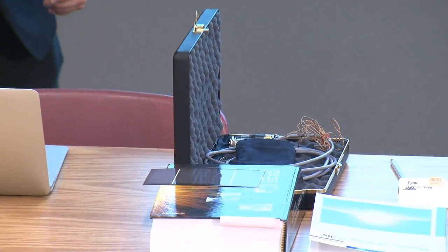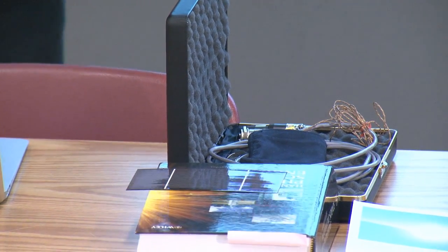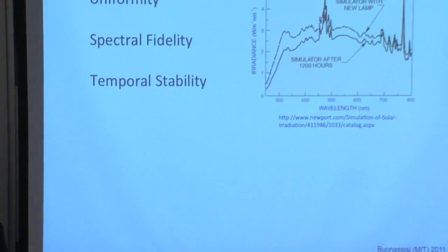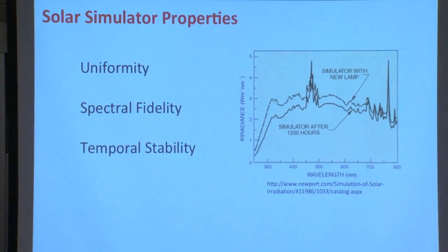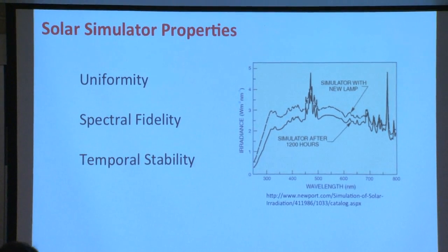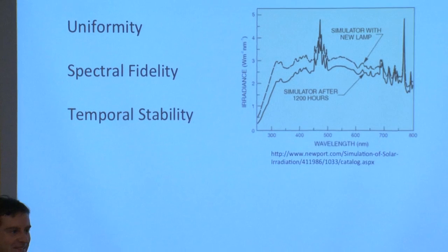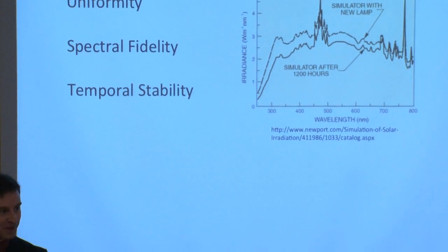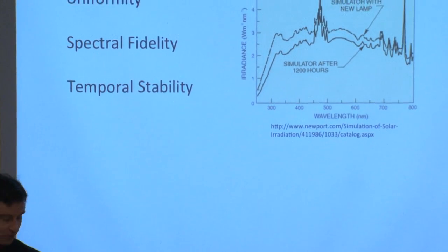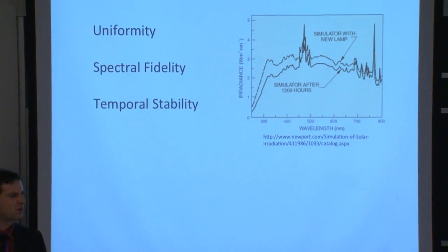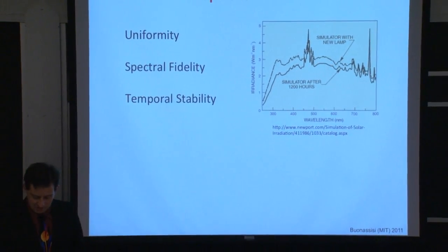When I say well behaved, what could happen? Well, one of the many things that could happen is that the lamp intensity decreases. That's probably the most common thing that can happen. You'll just have an overall reduction in the output of your lamp, in which case you'll notice a reduction in what cell parameter? Current, voltage, or fill factor? Current, right? So if light intensity decreases, you'll have a reduction primarily in your current, and a logarithmic reduction in voltage, right?